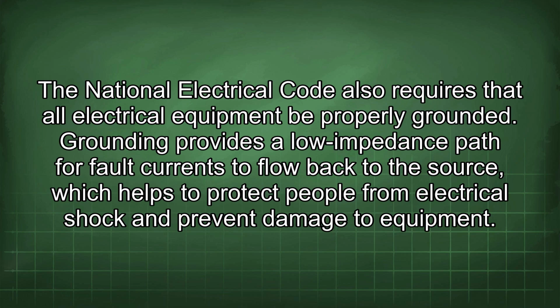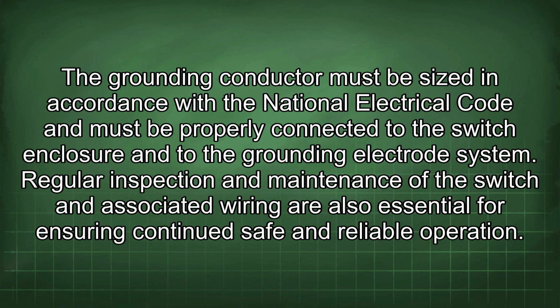The National Electrical Code also requires that all electrical equipment be properly grounded. Grounding provides a low impedance path for fault currents to flow back to the source, which helps to protect people from electrical shock and prevent damage to equipment. The grounding conductor must be sized in accordance with the National Electrical Code and must be properly connected to the switch enclosure and to the grounding electrode system.